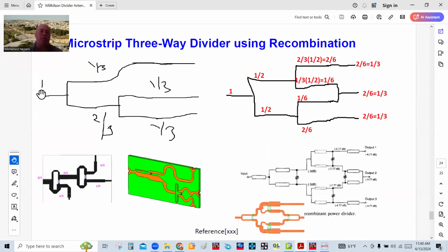So basically you take the signal, you split asymmetrically between 2/3 of the power here, 1/3 here, and then you split that 2/3 again to 1/3 and 1/3, and then you got, of course, equal power division for three ports. Now, the only issue with this is this output here is, as you can see, much shorter than the two other outputs, and therefore you need to add an additional line to this so that you delay it. It's a delay line so that you equalize the path differences.